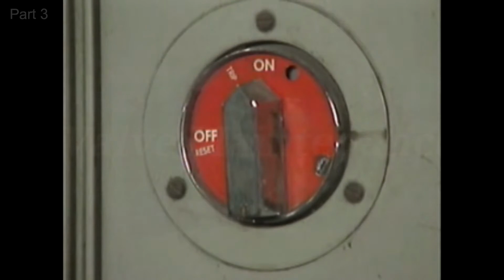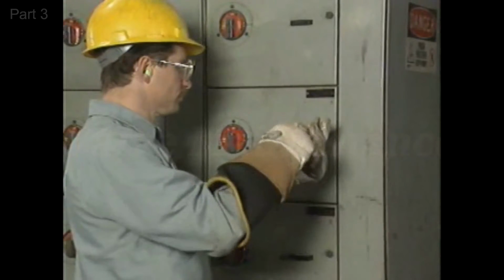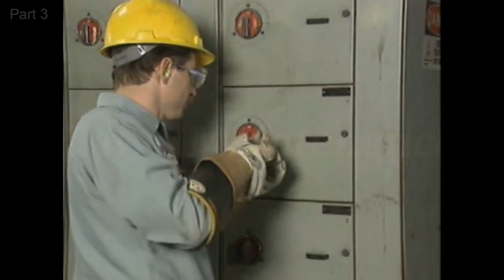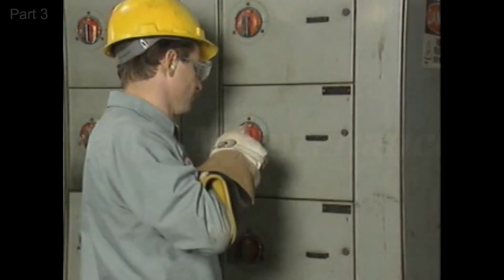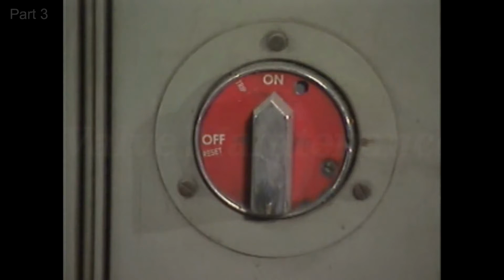In this part, we'll look at how you can troubleshoot an energized AC motor controller. Basically, there's one major reason for troubleshooting an AC motor controller while it is energized. Shutting down a controller can sometimes interfere with the operation of other equipment in the facility. For example, when two separate control systems receive their power through the same power supply breaker, opening the power supply breaker de-energizes both control systems, and that could be a problem.